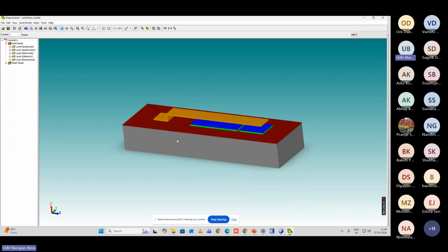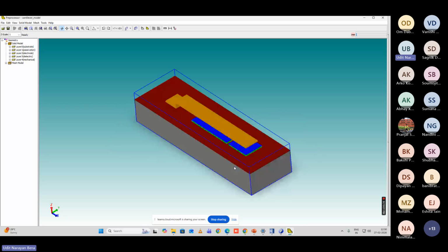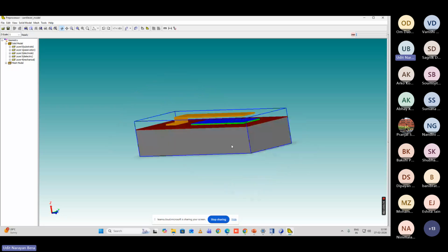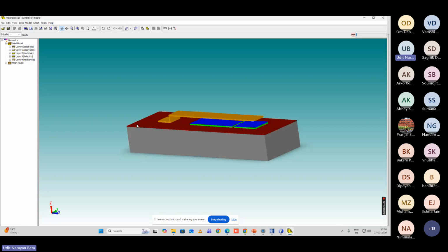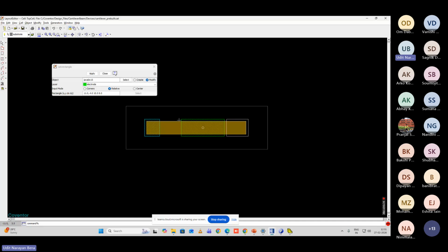You have seen the substrate level below already. Now, above that, that red portion was the passivation layer. Now, this electrode portion you can see here, if you look at it closely, the electrode is not fully covering the top of the surface. It is just at this position. Now here I want to show you how you got this. Can you see here that this green portion was the electrode? This green portion was the electrode. That's how my mask was set.